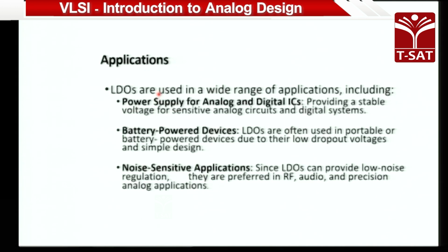Okay. Applications of LDO are power supply for analog and digital ICs, battery powered devices, noise sensitive applications. Let us say I have a particular block which is very much noise sensitive. So, instead of connecting the block to the main power supply which is coming from an external world, what I want to do is take the power supply through an LDO, and then create a power supply which is much more stable and flat, right.